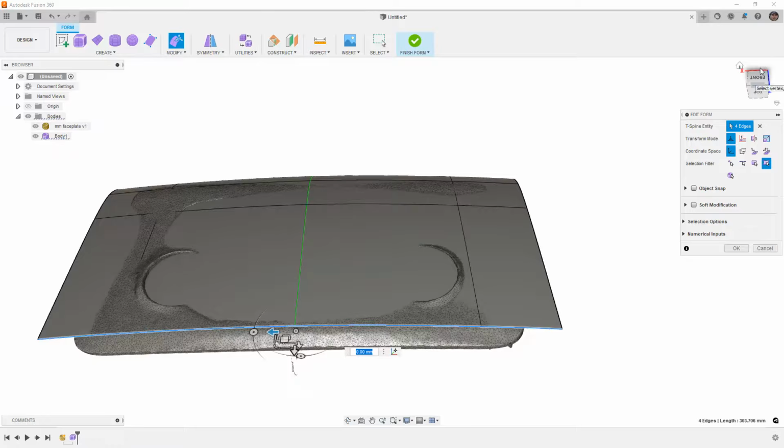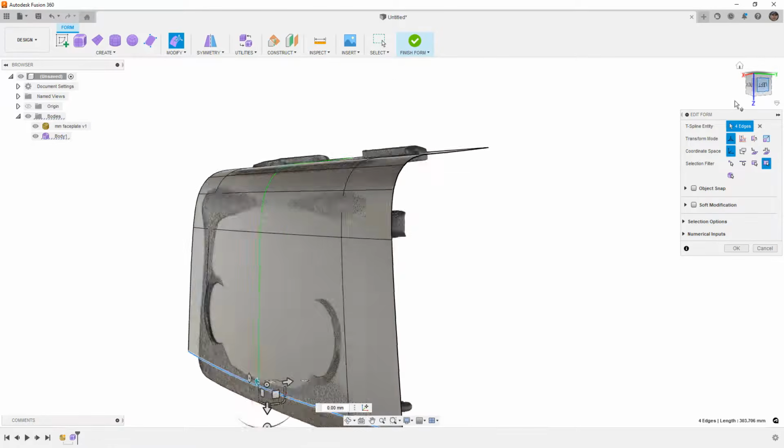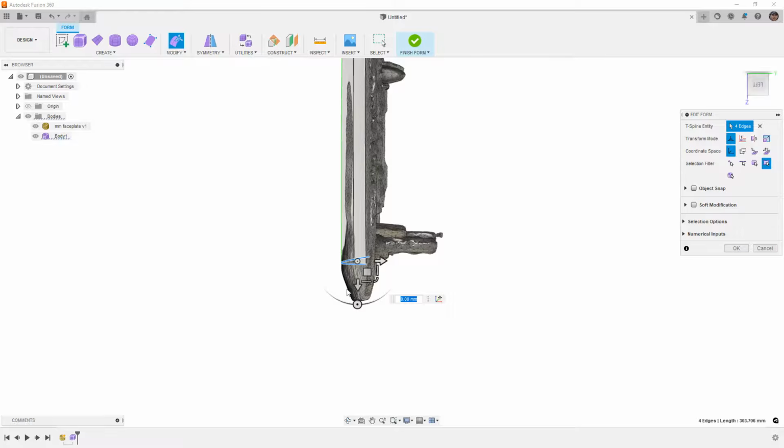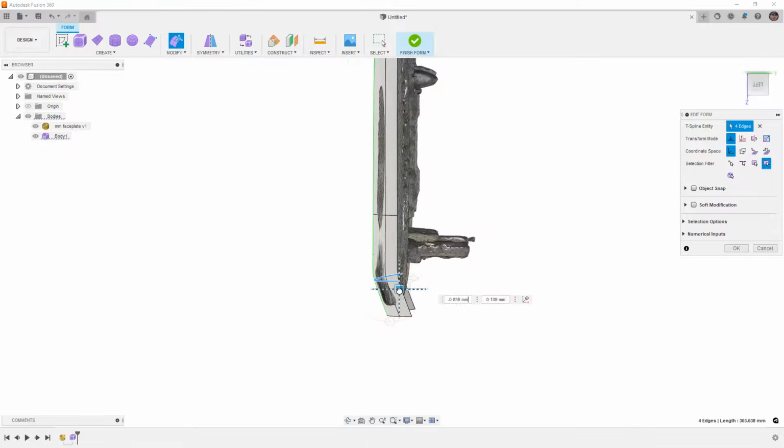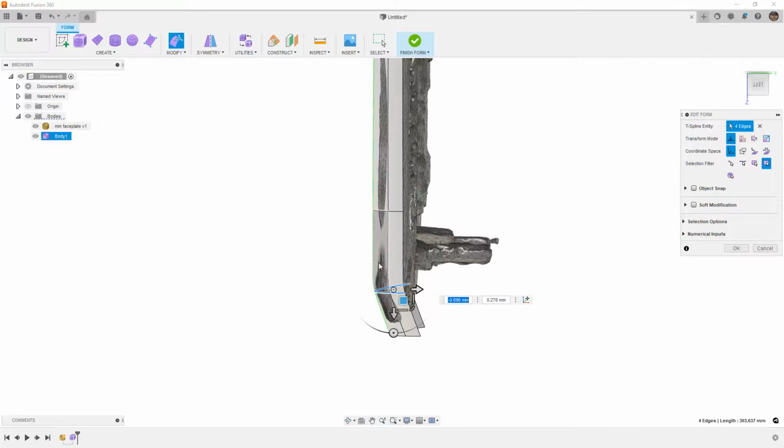I'm going to double click on this bottom edge. I'm going to go to a left view in my case, because this mesh is upside down, and we're going to begin to extrude it down. Now, in this case, because there is a harder transition, I'm going to extrude it a little bit. I'm going to let go of Alt, and then do it again to make sort of a second iteration in there, a second edge. And then I want to manipulate this edge a little bit. I'm going to pull it forward. And again, what I'm looking for is that very gradual transition. Now, one thing you'll note is that it looks like it might be going in and then back out. So I might want to pull this forward just a little bit, and maybe this bottom edge forward just a little bit.